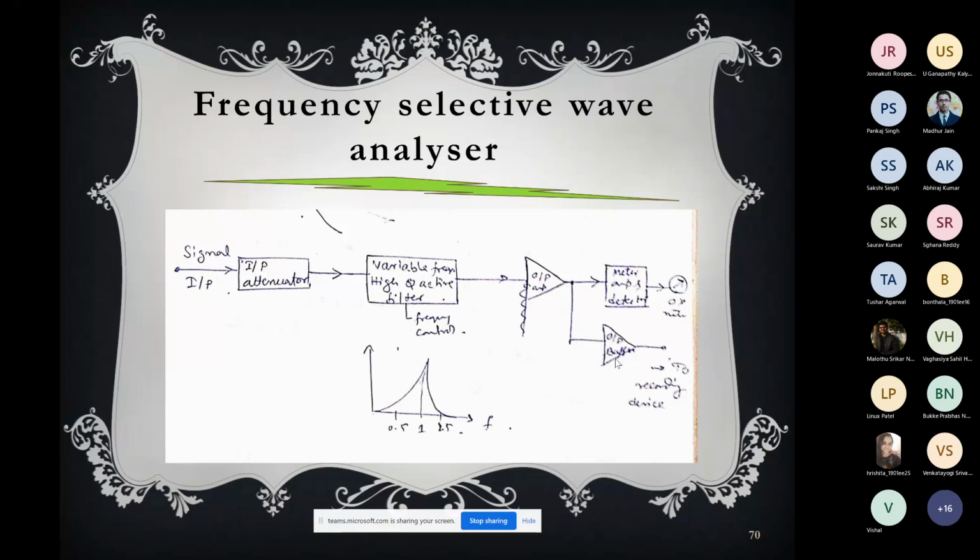Okay, suppose you have a signal in the time domain, say a triangular wave, which is periodic and varies with time with some period, and that can be represented as a sum of many sinusoidal waves. When you say sinusoidal waves, you have a frequency and an amplitude. So you have many frequencies and many amplitudes. When you plot those frequencies and amplitudes, that becomes a frequency domain representation.